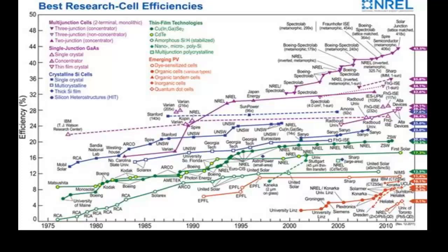Thin film modules have typically had the lowest cell efficiencies but at the lowest price, while crystalline modules are the most common types of PV panel type. On the other hand, some thin film technologies have real-life performance advantages over low to mid-efficiency crystalline technologies in areas with more diffuse light and higher temperatures, as they are less sensitive to such lighting conditions and thermal losses than crystalline technologies.